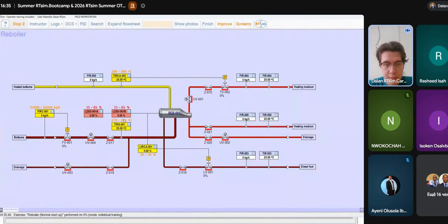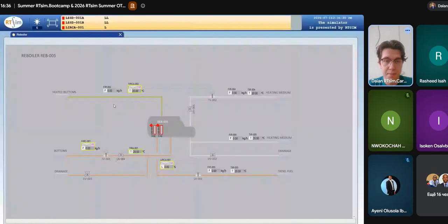And this device is connected with the emergency shutdown system and will directly stop and shut down all processes if the level in your boiler is less than 15%.